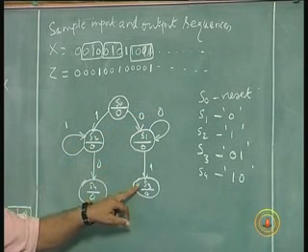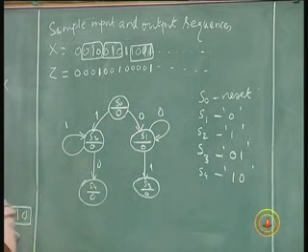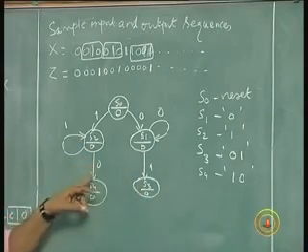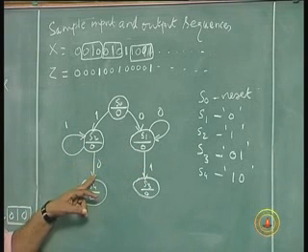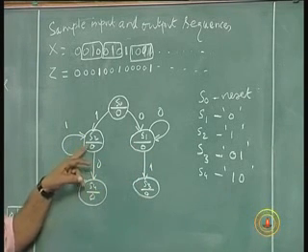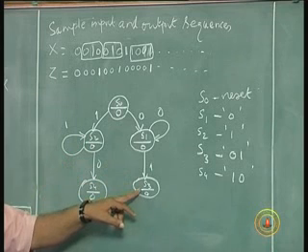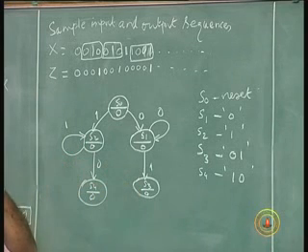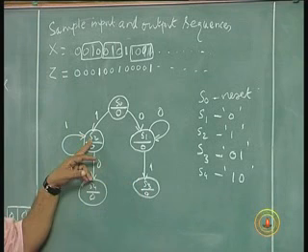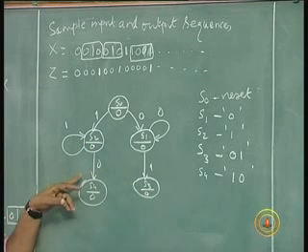So 0 occurs, pattern is complete. Do you have a question there? Yes. With this 0, can you go to S1? Which 0? From S2 on 0. Because it can be a new pattern of 0, 1, 0 starting off. But S2 means the pattern so far is 1, 0, 0, 1. If it proceeds, you get the pattern of 1, 0, 0, 1.